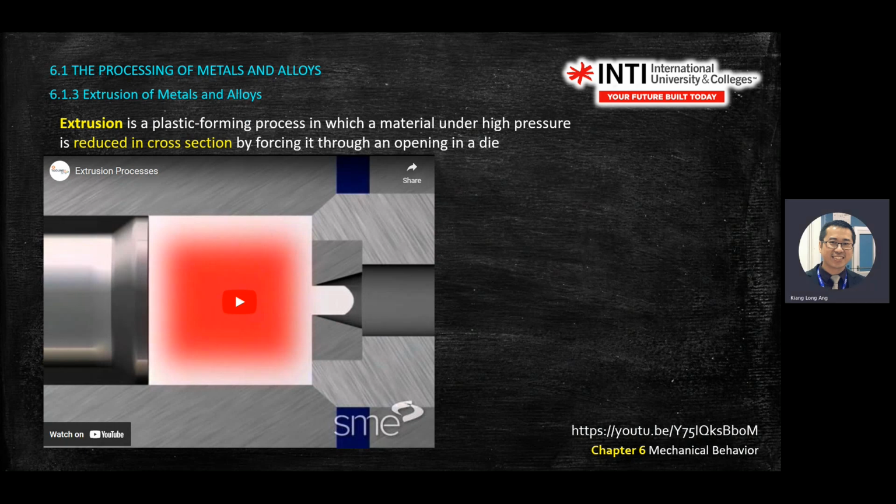If you plot the graph, let's say we have an ideal case, you will have a straight line on the tensile graph. If you get a straight line, what does it mean? It means you're in the elastic region, where you pull the metal and then you let go, the metal will go back to original size. This region is called the elastic region.